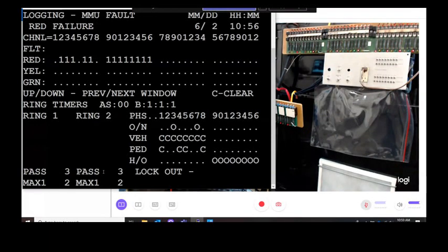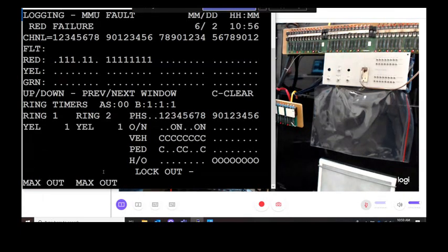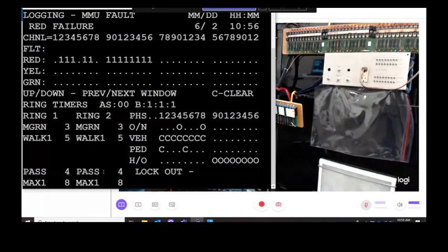So for this instance, again, we replaced the load switch. Red signal comes in a lot of different forms. Just think of it in the way that I probably have a 24 volt DC issue. So let me troubleshoot from that standpoint and work at it from that one.